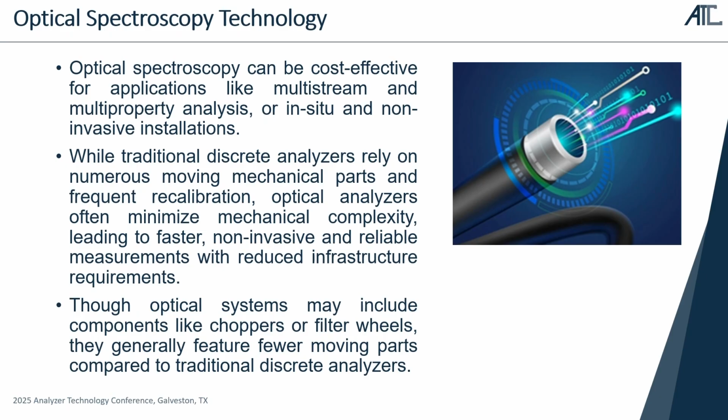Now, the important thing to mention here is that when we measure H2S and SO2, we have to take into account the sulfur vapors. These sulfur vapors can significantly change the spectrometry of the signal we are getting, and these concentrations have to be taken into consideration. Because these analyzers were based on analog electronics, it certainly was not possible to build a complicated matrix or systems based on modern machine learning in order to take into account these concentrations.